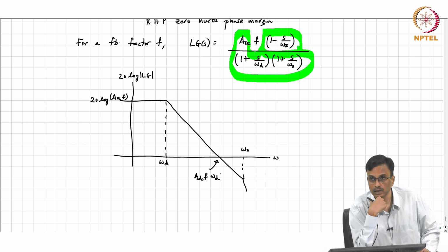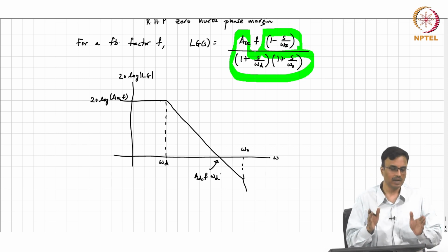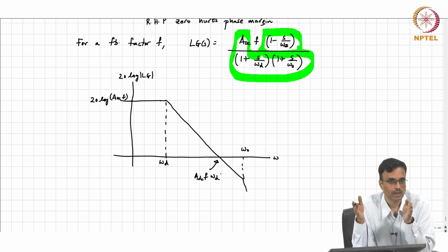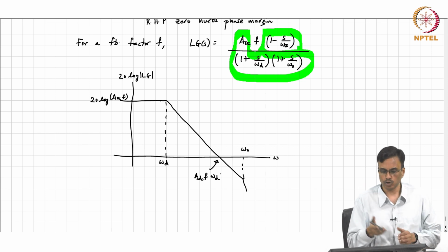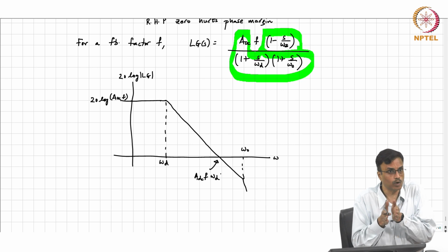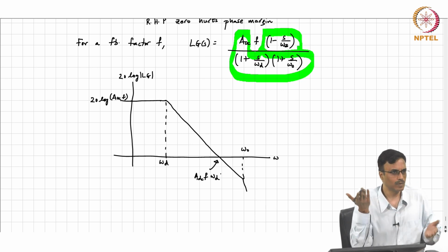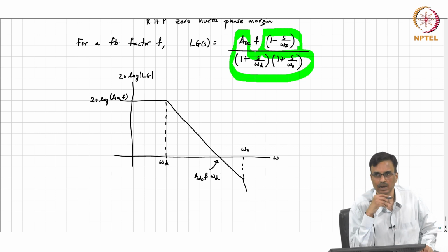Remember that for the feedback system to be stable, the unity gain frequency must be as far away from omega naught as possible, for good phase margin. So, as f keeps increasing, what happens? The unity gain frequency is becoming closer and closer to omega naught, and therefore, the phase margin will decrease. In other words, the system is getting closer to becoming unstable.